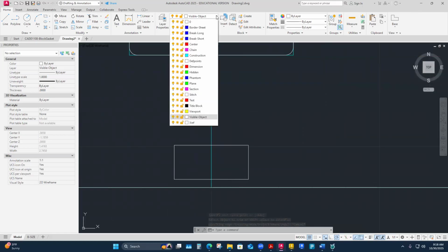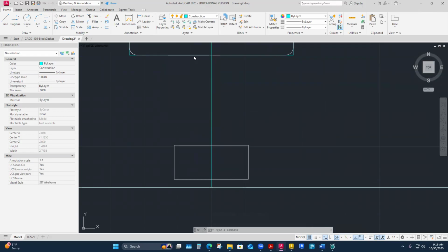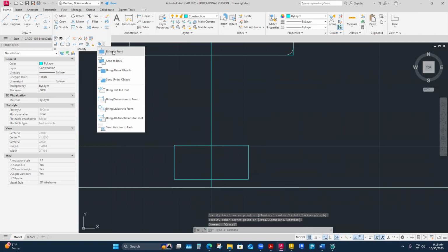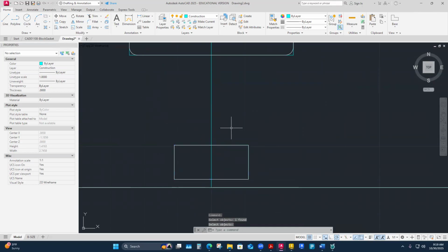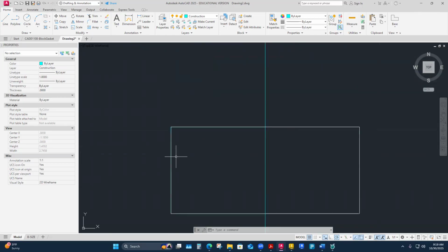I might do the same thing here. This has radius, so I might take a construction layer here, and I might just trace this with a construction rectangle, really, just so I remember where it's like, and then I might send that to back or something if it'll work for me. Send to back this thing. Yeah, now I've got my visible lines on top. Because I'm going to radius all these corners too. They're like a real small radius, 0.005, like 5 thousandths of a radius on these. So they're pretty small fillet radius of 0.005. I'm going to do multiple all the way around this thing.